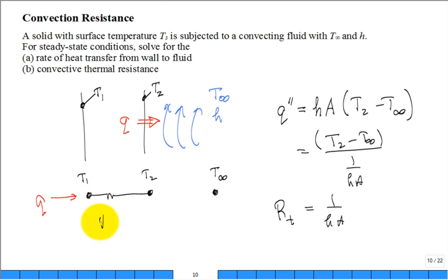That slab has a thermal resistance, L over Ka, as well as the resistance to heat transfer coming off the surface and getting into the fluid. That thermal resistance is equal to 1 over HA. So you could put resistors in series. Aren't these 2 resistors in series? Yeah, absolutely. You can sum the 2 resistances.